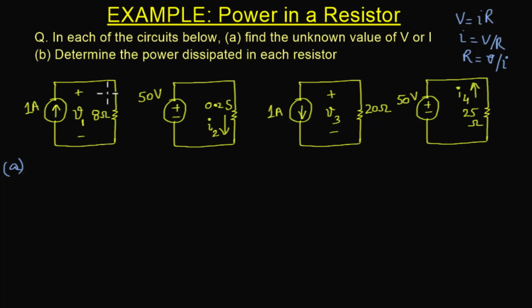One important step you need to do before solving any circuit problem is to assign one of these conductors as ground, okay? Because voltage is the difference between the potential of two terminals. So if we say one terminal is at 0 volts, then the calculations become much simpler. So let's assign the lower point as 0 volts, and that is represented by this symbol, which is called ground. Now we have said this is 0 volts. All the voltages at other points would be with reference to this voltage.